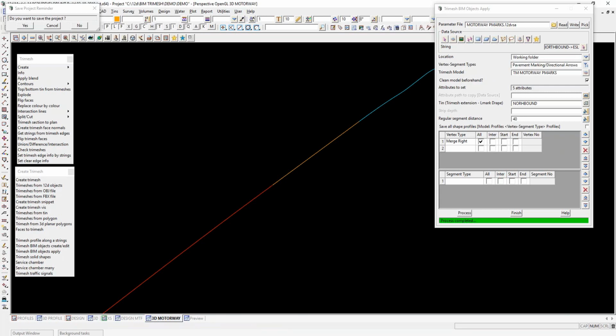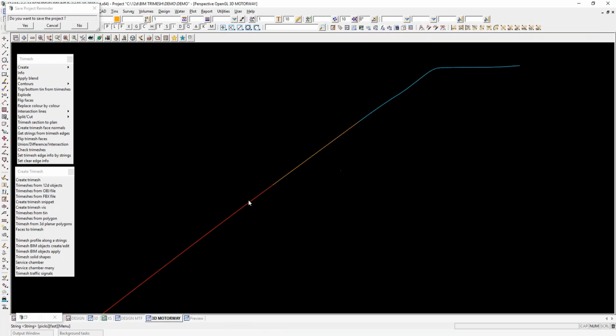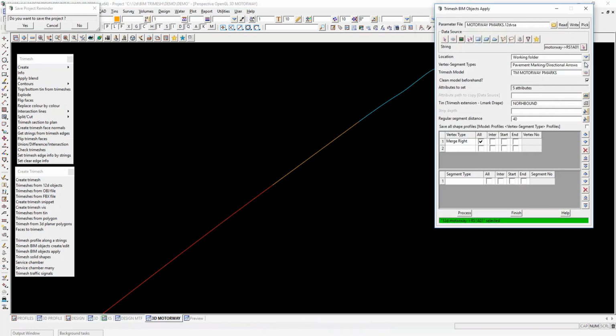In that case here, we had a bit of a quick look before at a bridge and a motorway, but I've created some strings in here down my road centerline. All that's in that MTF that I used was an insert string for the motorway, a bridge, and the continuation of the motorway. So I go and pick that string, and I drop down.